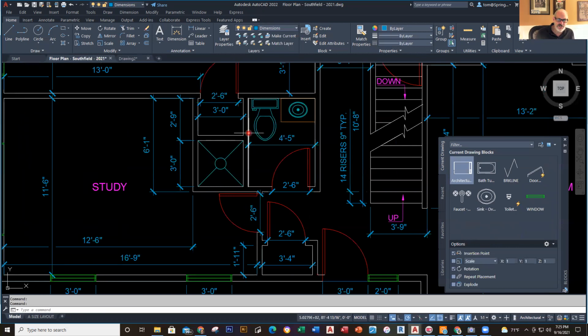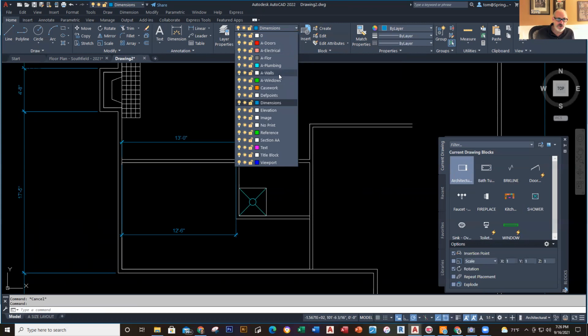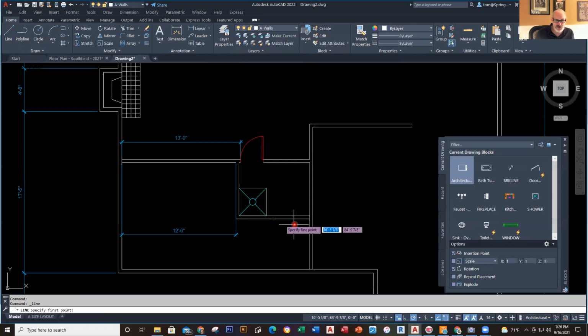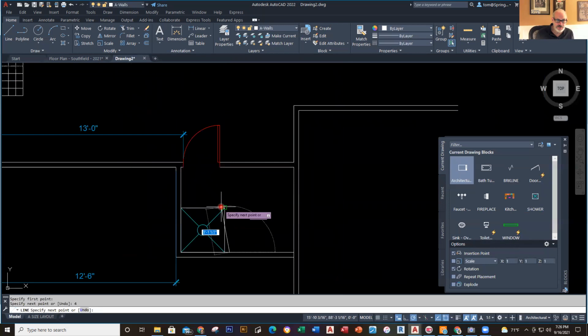So then I've got a wall here. The wall goes here. And then when I put that in, we are good to go. That basically puts us in a good spot. So now I'll go to my line command, going back to the wall layer, A walls, and I'll go to line, and I'll just go here, and I want to go from here over a distance of 4, and then I'm going to go up. Offset this one over like this, and then go like that.